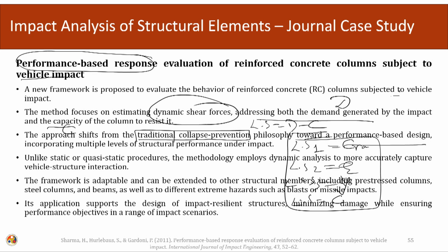So, unlike static or quasi-static procedures, the methodology employs dynamic analysis to more accurately capture the vehicle-structure interaction. Whatever we have learned till now, the multiple degree of freedom analysis, we will apply this to evaluate the response of the system. The framework is adaptable and can be extended to other structural members including pre-stressed columns, steel columns, beams, as well as other extreme hazard events such as blast or other types of impacts also.